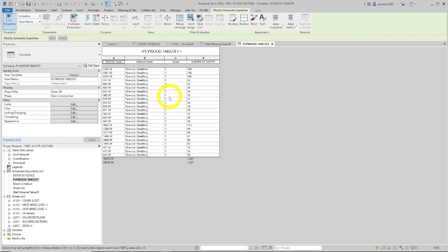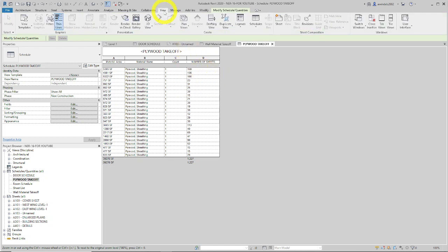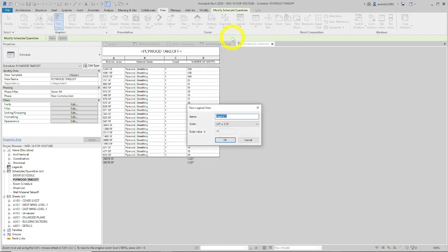And another very common one are symbols legends, so like section view headers and keynotes and all kinds of little bubble notes we're about to put, or titles to sheets. Those are different drawing symbols, so they all can have different legends, and they're very common, and they can be a pretty comprehensive list, but we're going to start by learning how to add some of these. And all it has us do to start is go to the View tab. There's a new area for us, Legends, and Legend button.